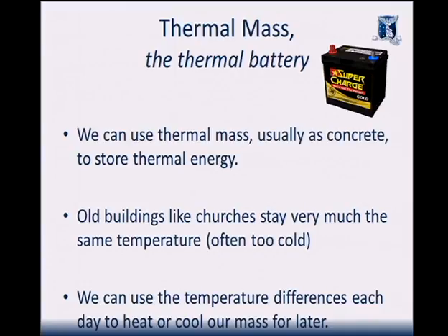That thermal mass would stay more like the temperature of inside, wouldn't it? Because it's touching the air inside, it's not cooling down from outside. You might then say, okay, well, isn't that going to get too hot? And the answer then is, well, okay, now what we've fixed the heat loss problem, we're storing heat, and sometimes it's too hot, yes. So what do we do?